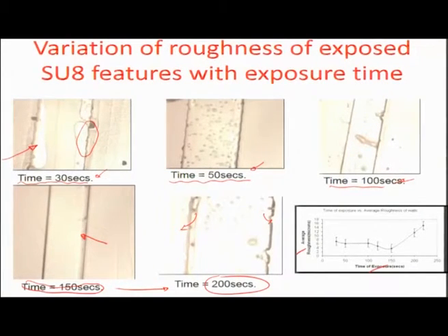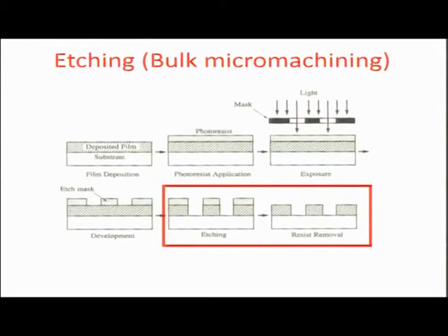Okay. So, it is very carefully planned and drafted if you want to have a good patterning process on the system, and every patterning process has to be developed ab initio by looking at the various resist parameters and then trying to balance out the times, the thicknesses, the spin speeds, the heating times, the development times, so on and so forth.